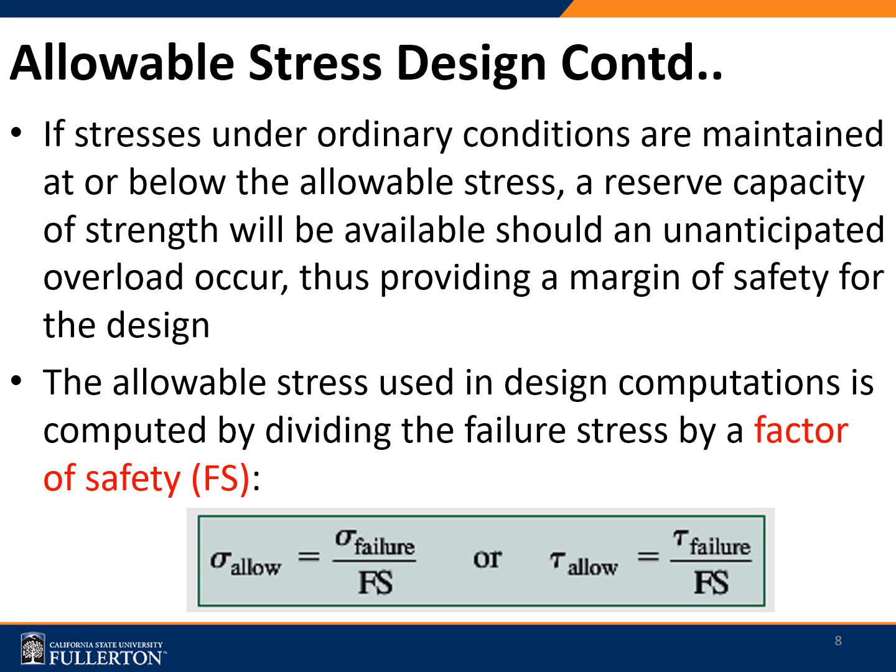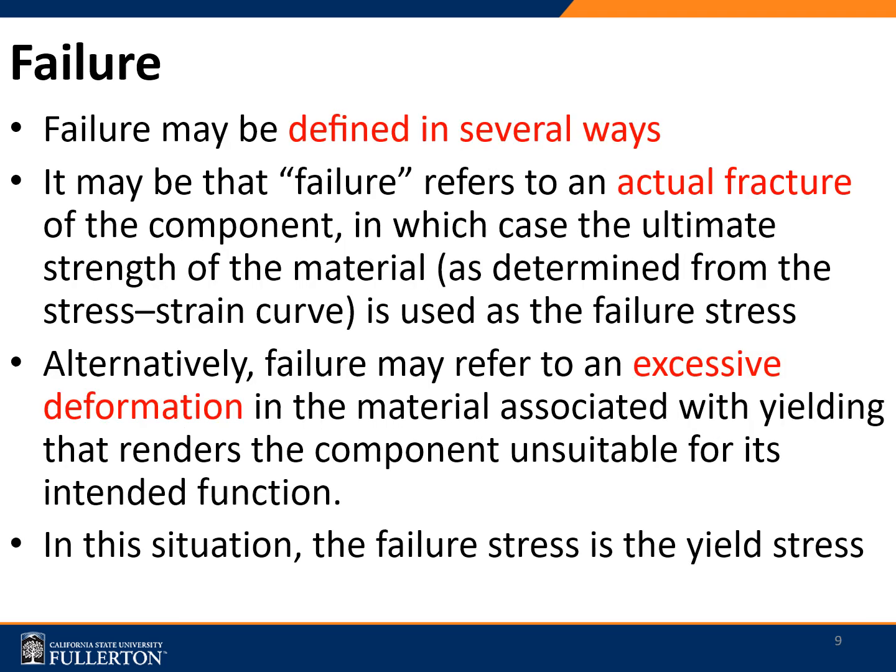In case of shear stress, it will be the same concept. It will be the shear stress at failure over the allowable shear stress. Now the failure can be defined several ways. As I mentioned before, you could consider failure as the ultimate failure, the actual fracture, or even a small amount of yield stress. A load condition that exceeds the yield stress of the material can also be considered a failure. So there are different ways people could interpret failure, and depending on that interpretation, you have to decide the structure with the necessary factor of safety.